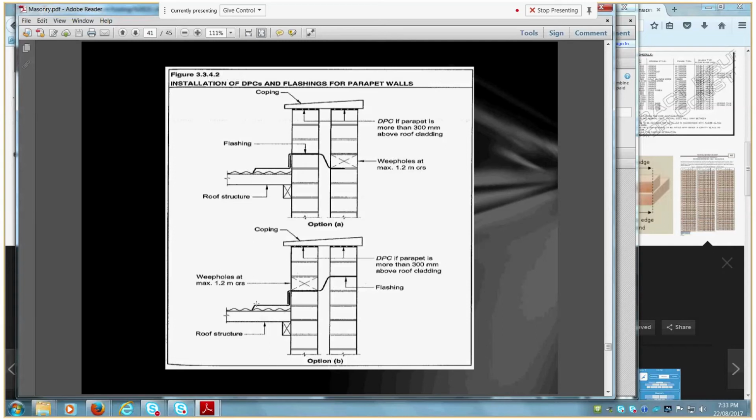Alright. See like the last one, that looks more like the parapet. Yeah, see the one there and the one on the back. That one and the last one there. Yeah, this one here? Yeah, more like a parapet. Well spotted, yeah. So that one will have a roof sunken down behind that parapet wall there. And it doesn't matter the direction of the roof, whether it's going down or up, it's always called a parapet.